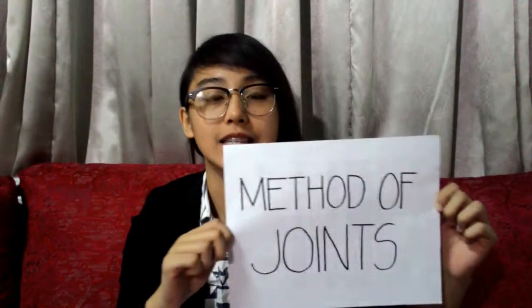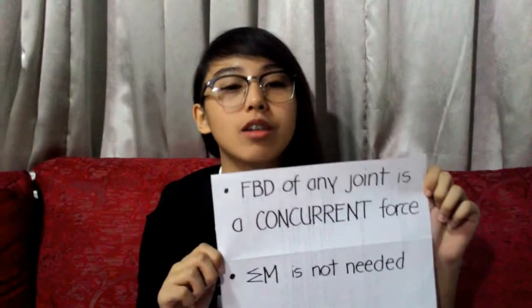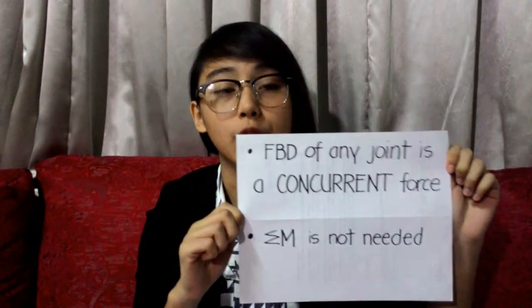Hi everyone! Today, we're going to discuss the method of joints for analysis of simple truss. The free body diagram of any joint is a concurrent force system in which the summation of moment will be of no help.